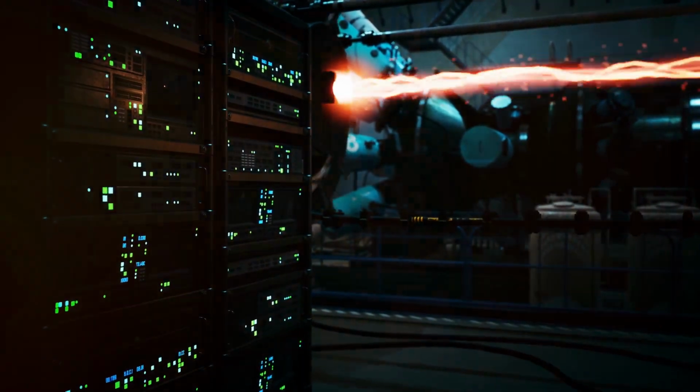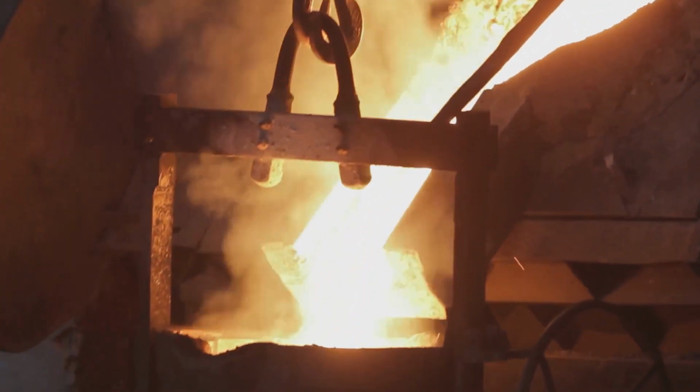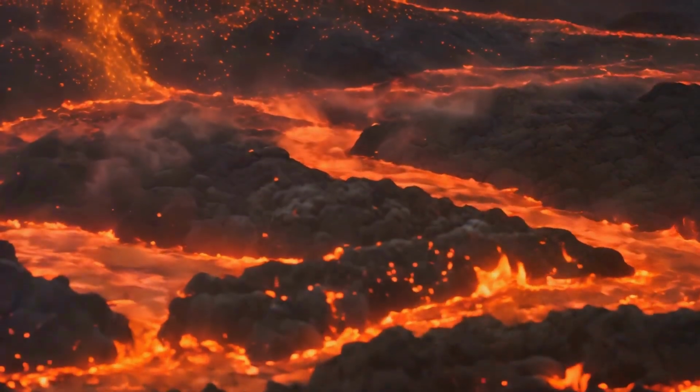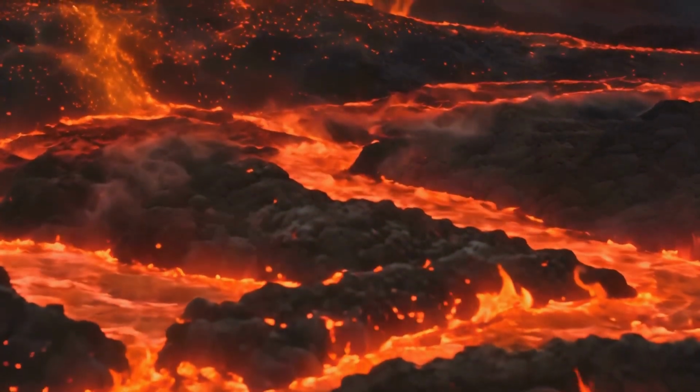Section 7, Rosseland Model. When the medium is dense with photons. The Rosseland model is like swimming through a thick fog. It's used when the participating medium is optically thick, meaning radiation can only travel a short distance before being absorbed or scattered. In such cases, the radiation field becomes diffusion-dominated.